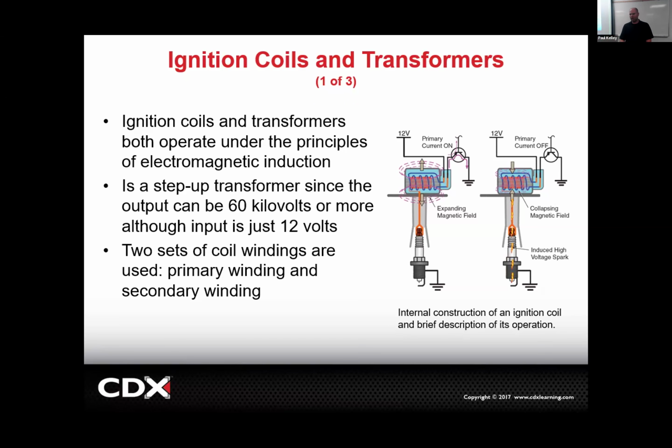Why would you want 12,000 or probably 60,000 plus? Well, when you go to spark a spark plug, remember the spark plug has to arc that gap. To jump a gap, it has to have really high voltage, right? Electrical pressure, more pressure to jump a gap. So when we go to spark the spark plug to ignite the fuel, to do the combustion magic that we have, right? You hate those EVs and electrics. You like ICE, internal combustion engine. You like vroom, vroom.